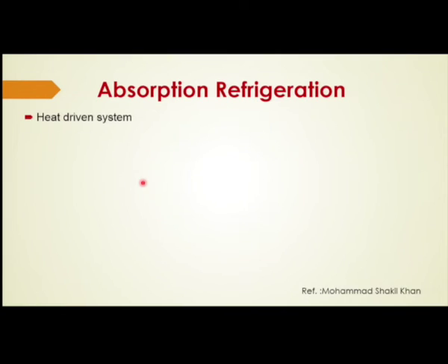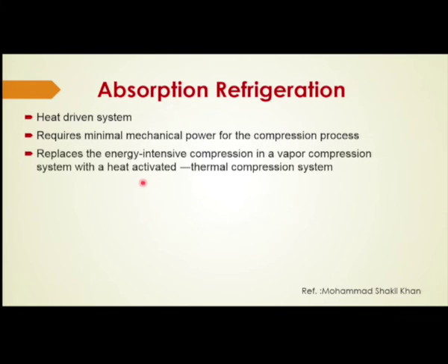The next type of refrigeration we are going to see is absorption refrigeration. It is a heat driven system. It requires minimal mechanical power for the compression process. It replaces energy intensive compression in a vapor compression system with a heat activated thermal compression system.